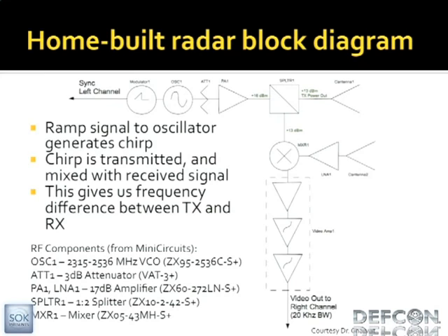And then there's this thing down here called a video amplifier, and what that does is it basically takes that really small signal that's still pretty small, and it amplifies it a bunch of times at low frequency so we can feed it out to the computer. And there's 2 outputs to this. One of these is the sync pulse, which basically tells us when the chirp starts, and the other one is the actual data signal back out.